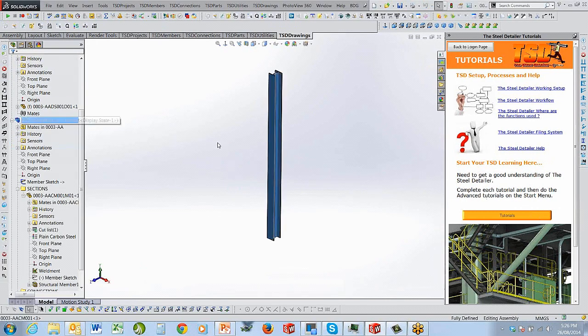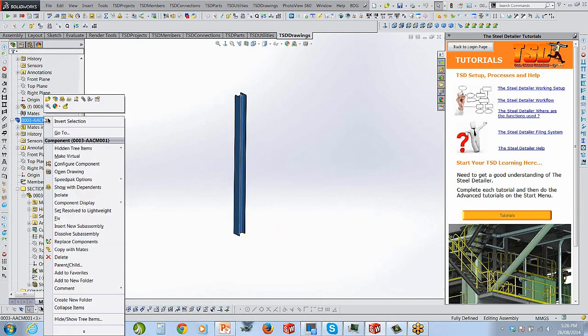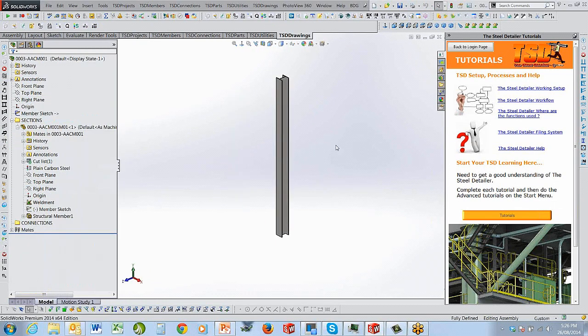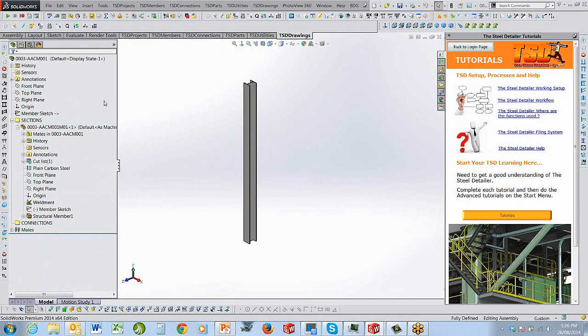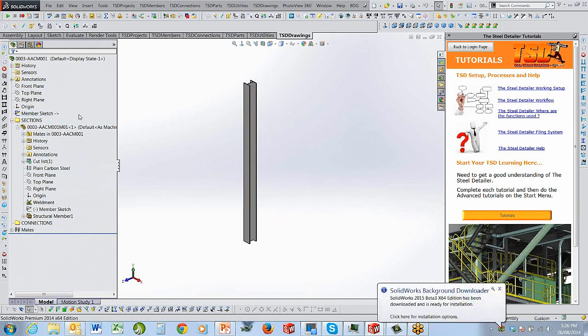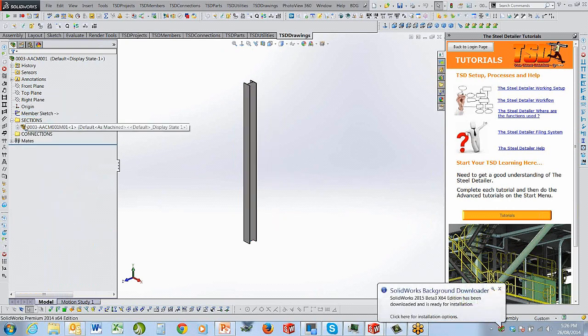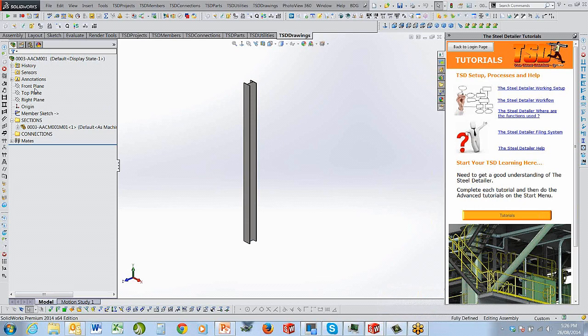So what this means is that now if I go back into my weldment member, I can build my frame quite simply off a member sketch that's already in there. So I can peel all this back, and this is a driving sketch within a welded member. You can do this at the assembly level. It's not a big drama. Or you can actually insert a driving part. I know that might be a little confusing.